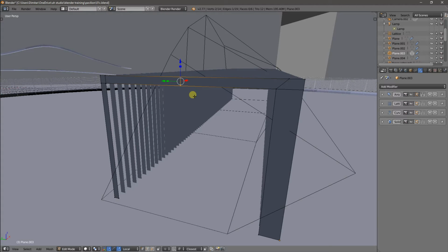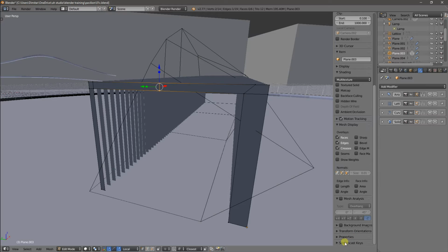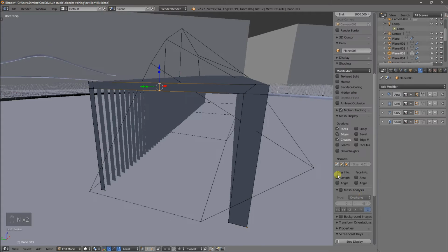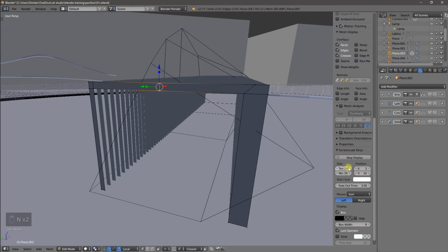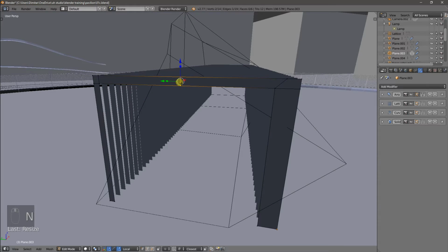And now we'll bevel. Oh, I haven't turned on my hotkeys so you can see what I'm doing. Here you go. Let's make him a little bit larger. Okay, so now if I press W, bevel, and we'll bevel to an actual size, we can input a number, 0.1. And again, remember with any of these commands, if we go into our tool shelf here,